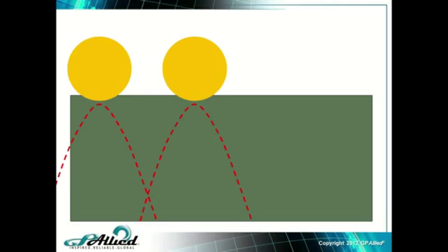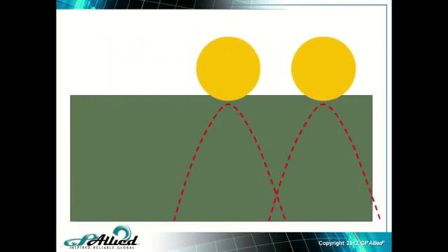Now, every roller has a stress cone, if you will, that it takes with it as it rotates around the inner race, inside the outer race, especially as it goes through the load zone. So if we were to watch this spot right here, where my arrow is, we can imagine that it's relieved, but the moment this roller goes on top of it, it compresses, and then when it gets in between, it relieves, and then it compresses and relieves. So let's watch that. If I set my arrow right there: relieved, compressed, relieved, compressed, relieved.